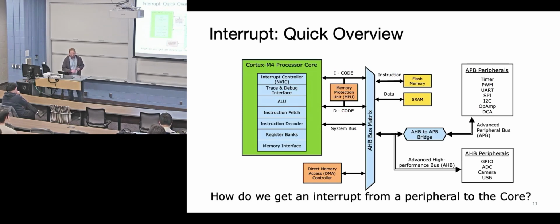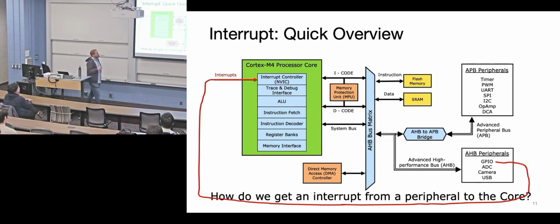We presented this slide before, but how do interrupts interact with the core? How does the signal get there? Yeah, there's a wire, a red wire in this case. Remember the red wire? You could think of it as an extra bus structure, although it's not formally a bus, but there are at least 96 wires coming from the peripherals in your particular microcontroller over to the NVIC controller that's inside the core. Those wires go high.